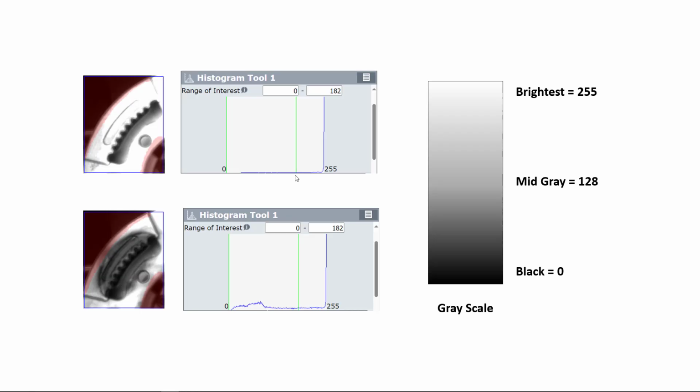I'm going to show you in this illustration how this study works. The grayscale goes from 0, which represents black pixels, to 255, which represents white pixels. So selecting the range is selecting, on the grayscale, the range of pixels that we're interested in measuring. The result is going to be called in range, and it's the percentage of pixels that fit in the selected range of the grayscale.